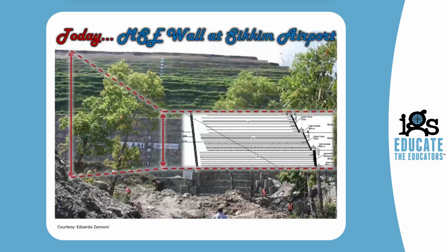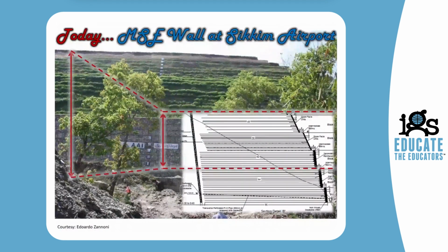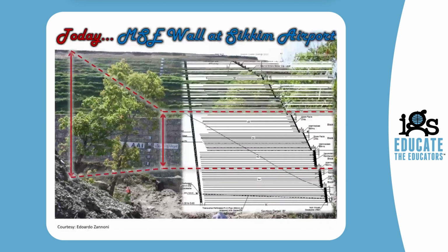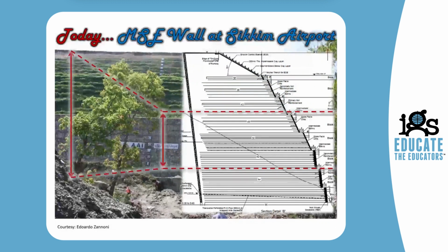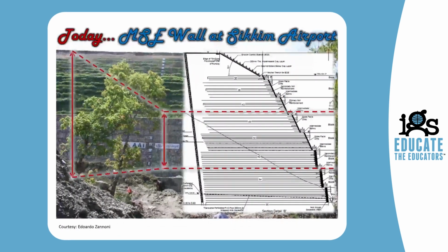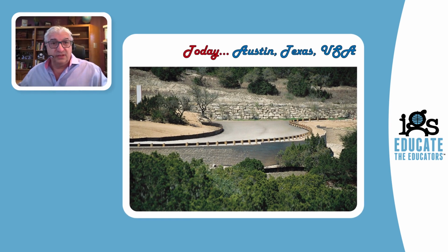of reinforced soil system, but you do not see that behind this facade there are very high strength geosynthetics to provide internal and external stability to this retaining wall, but also you do not see traditional terraces going below this view of the picture. And also what you do not see is that this was taken during construction, so there are 3 additional levels in this structure. This is probably the tallest geosynthetic reinforced wall in the world today. But not only do we see impressive structures like the one in the Sikkim airport, we also have everyday structures.